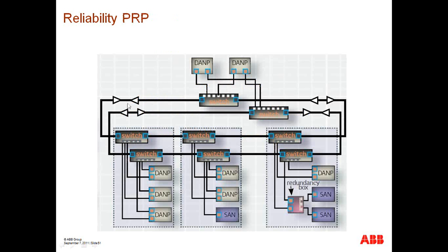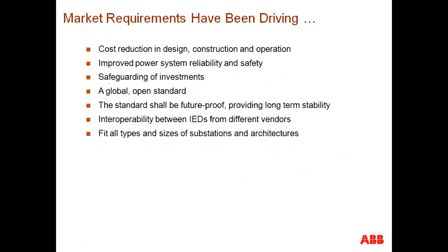But it's also important to take into consideration the redundancy of the network. And there are actually two technologies, HSR and PRP, and we're going to talk from the PRP perspective. PRP stands for Parallel Redundancy Protocol. The idea of PRP is to have two simultaneous networks running in parallel in such a way that traffic is replicated. And if you have a point of failure on one of the networks, there would be no impact on the delivery of the information from point A to point B, since the parallel path or the parallel network should not have been affected by that particular event. So the idea, again, is you essentially have two parallel paths to deliver the information from point A to point B, and that is, in a nutshell, what it is.